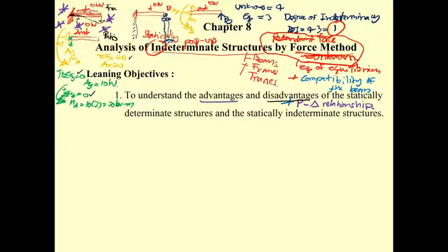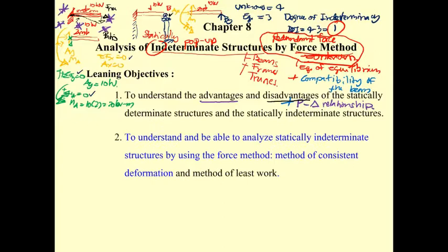Okay, the determinate structure you can analyze easily, but the determinate may have large deformation. And statically indeterminate, you're going to build more supports, so the cost of construction may get bigger. And the second, this is a very important part that you understand and be able to analyze the statically indeterminate structure by using the force method.